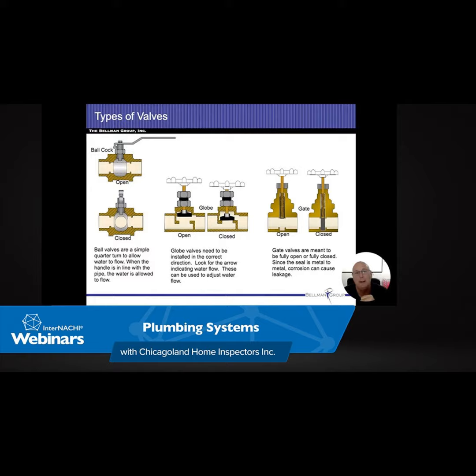But even with that, in Chicago, they're making a big push to put water meters in all the houses. So they're actually cutting that egg off, and there is no more bulge or egg-shaped thing at the end. It's just straight on, and then the valve, and then the water meter that's there. So if the pipe itself is curved, it's probably going to be a lead pipe. If it's hard and straight, it's going to be a galvanized pipe.